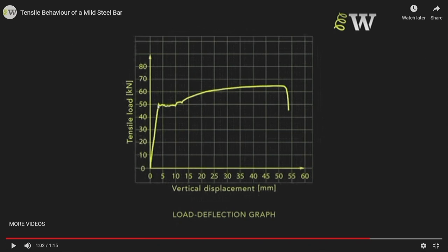Now, when you do the material unit, you'll understand what yielding means. It's the rearrangement of the slip planes. So they slide past each other at that load, and then you'll start to get a quick displacement without any increase in load. And that happens here, called the yield plateau.